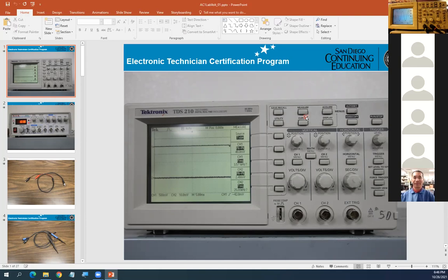Now, you only press auto set measure when you're changing something in the generator. When they want it now to be 6 volt peak to peak, 10 kilohertz, then you have to work with the generator, right? Right, to get this signal. And after that, you must press auto set measure for the scope to re-trigger and display with the update from the generator.